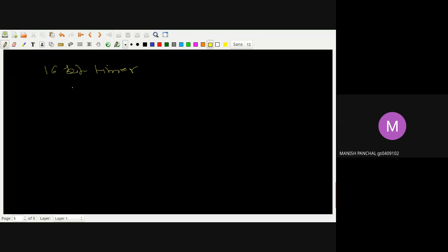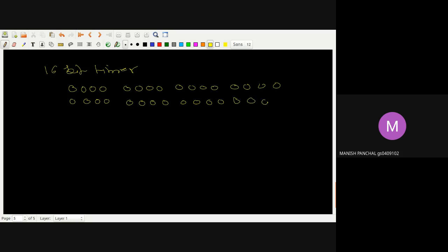So if I say that my first value is in binary, it is a 16-bit timer or counter. It has started to run. The next value, after some predetermined time, will be incremented by 1, and it will go on like this. Finally, because it is 16-bit, it will go up to the maximum of 1111 1111 1111 1111 in binary. So we can say this count timer started from zero, and in the hexadecimal number system it has reached FFFF.